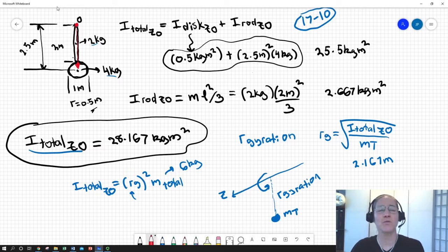Most of the time you're going to be really concentrating on the free body diagram, on the kinematics of motion, which is where, like it or not, you're going to get a lot of the equations you'll need to solve. Moment of inertia is in a lot of cases going to be kind of the simplest part of the problem. But if you don't get it right, one of your fundamental equations of motion is not going to be correct. So it's very important that you're able to calculate your moment of inertia correctly about whatever point that you're summing the moments.